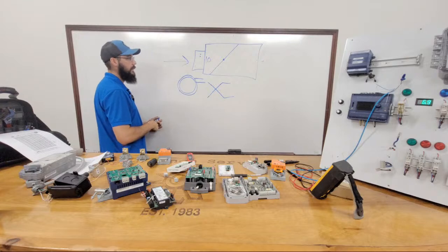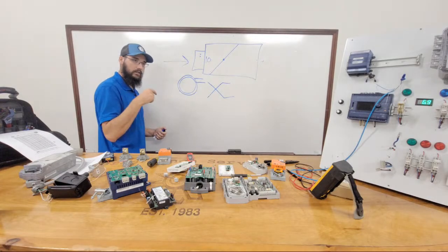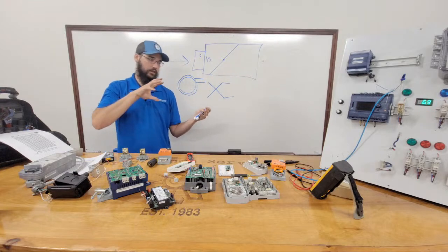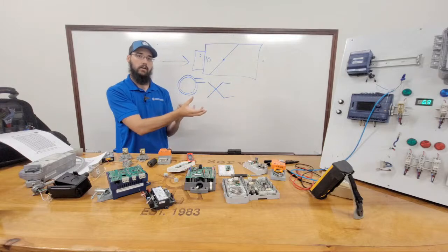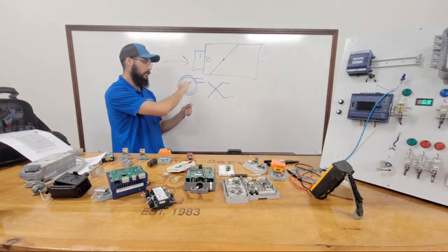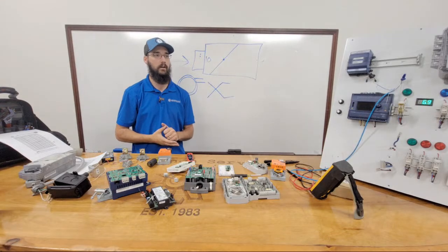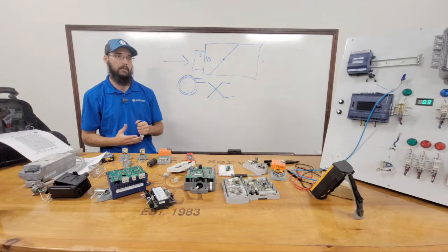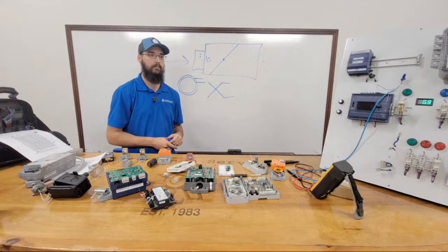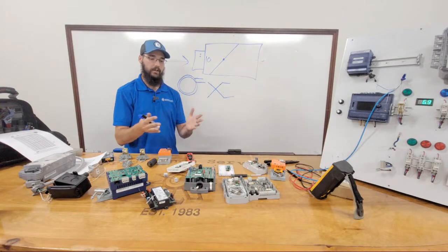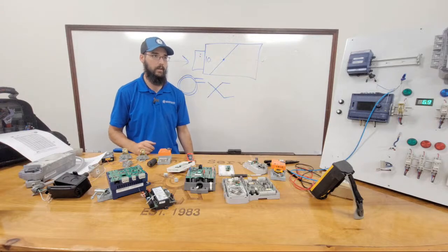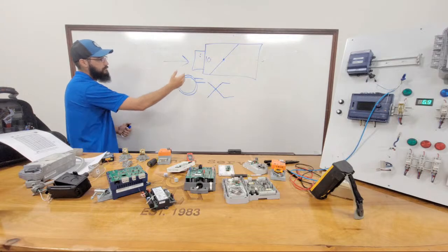The reason for that is the flex duct has a spiraling feature in it. And that spiral creates a significant amount of turbulence on that airstream, to the point where that turbulence just completely throws those pickups haywire, and they can't register properly. Since they can't read properly, you'll never be able to get them to work. And whatever readings you have on your computer are useless. So be very careful with that.